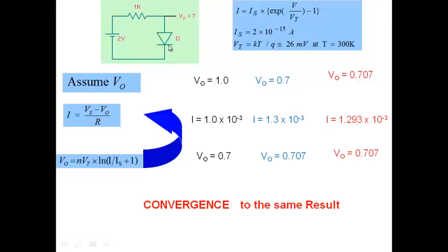Obviously, you can see here for a one diode circuit, I can do that. But for multiple diode circuits, multiple sources, this is not going to be easy. Okay? It's not going to be easy. It's not something that I can take paper and pen and work out for multiple diode circuits here. So this iterative method is more suitable if you take your circuit and transform it. As I said, all circuit analysis is taking a circuit and transforming it into a set of equations. So if you have multiple diodes, transform it into a set of equations, write a computer program which will do this for you, which will take a guess and then go through all of that. So it's ideal for a computer implementation rather than working out with paper and pen.